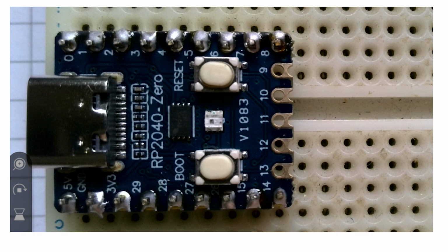It also runs quicker. I'll explain later on that the faster the controller's running, the better for NeoPixels. You can't run a NeoPixel on a 1 MHz controller. It has to be at least 12 MHz, which is an Uno. Faster than that is better. Slower than that, it won't work, for a reason that I'll explain.